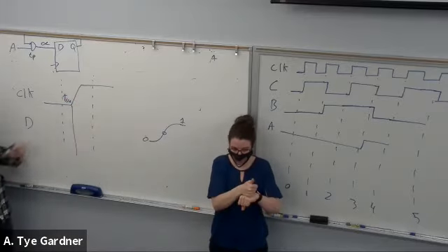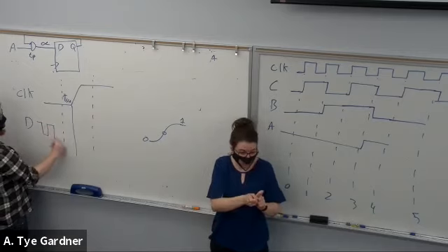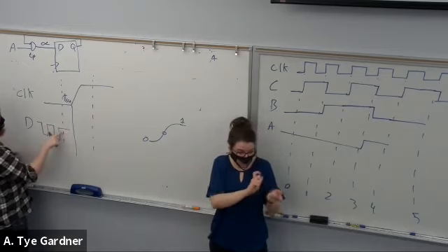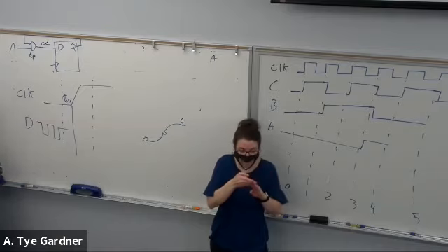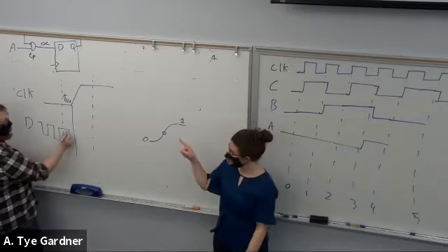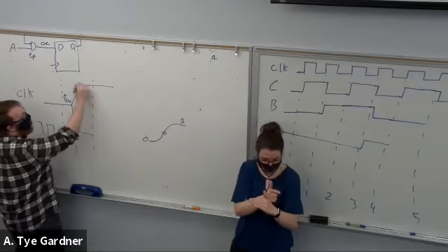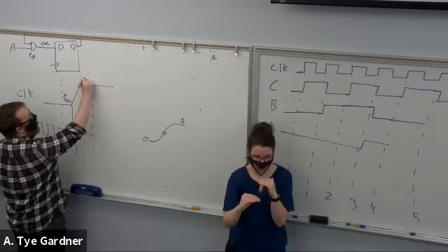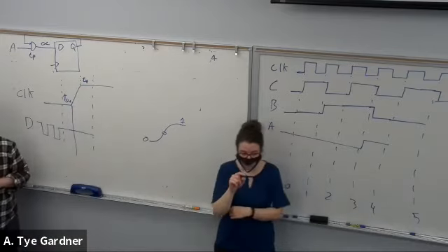So your input can change all at once before here, but then must be stable before that setup time difference of the clock. It needs to hold stable at least until T hold time after the end of that clock.